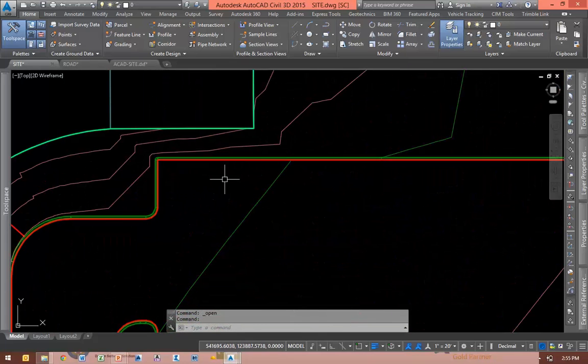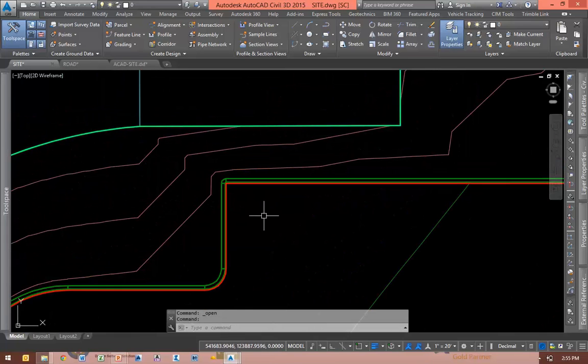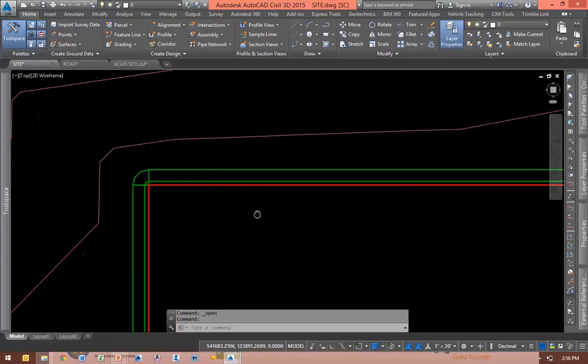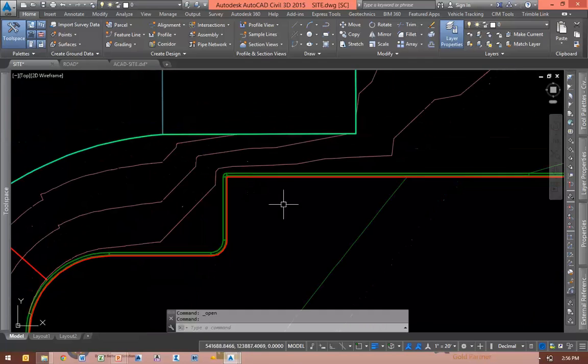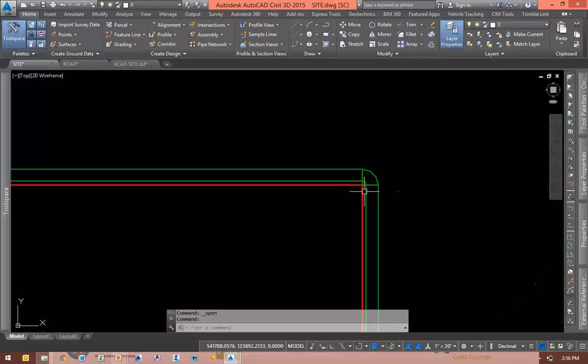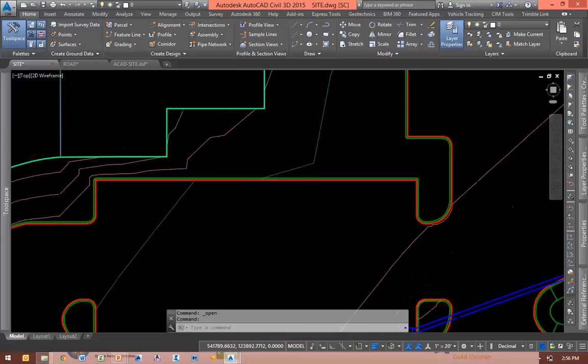Next thing, we're dealing with feature lines and curb gradings in Civil 3D. They might be grading these in different ways. In this case, I have some grading objects. We might have been using some stepped offset feature lines, for example. A lot of times what we want to stake is back of curb. Any of you guys who are using grading objects, you get this little loop-de-loo thing here, right? And you want to stake this right here. So what's the simplest way?